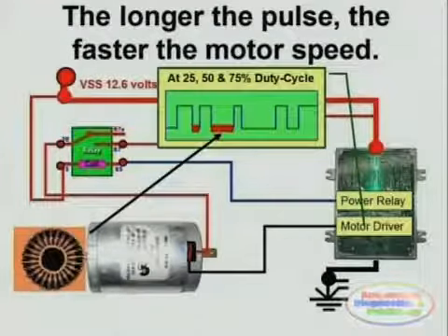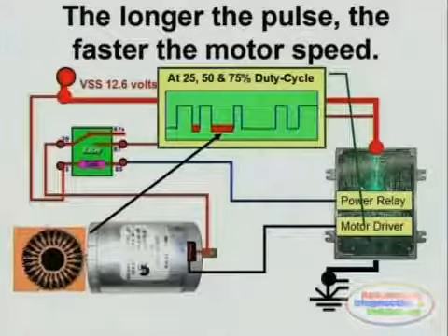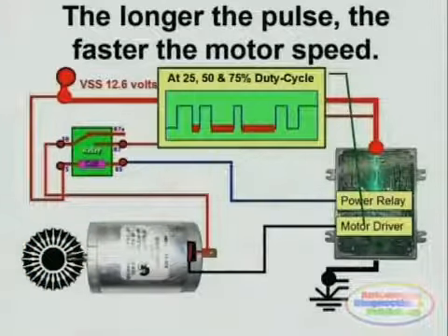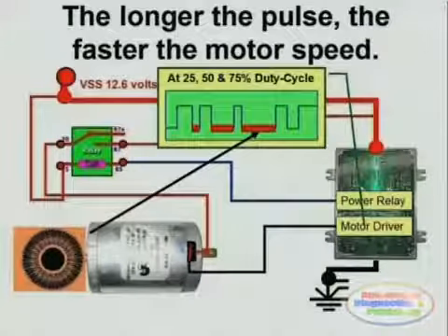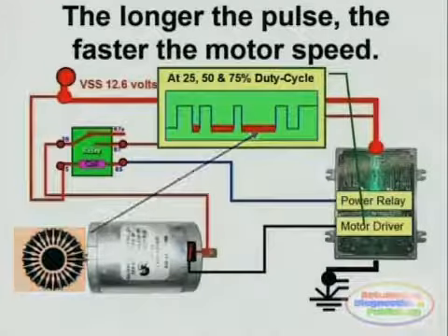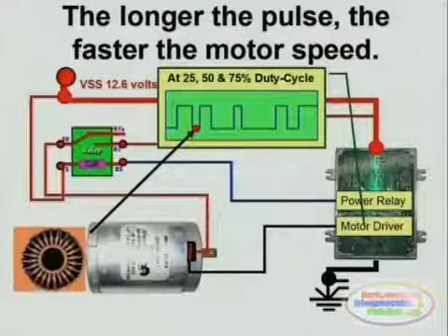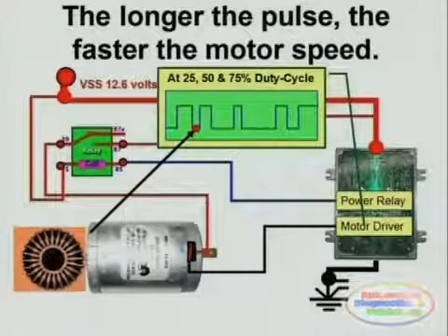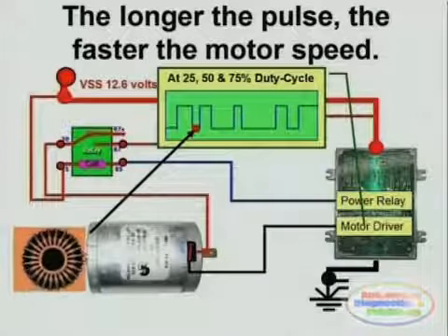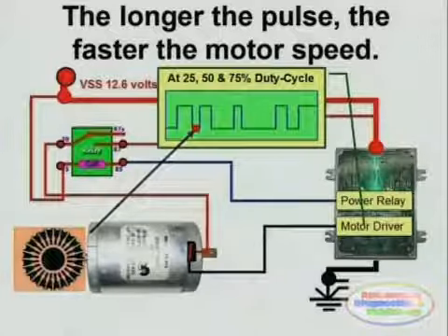Remember that this is a repeatable wider pulse, and it is not repeated here in this diagram for sake of explanation. But the longer the pulse, and now we can see that the fuel pump is turning even faster. The longer the pulse, the more work that the component is going to perform. Again, here we see a very short or very low duty cycle, probably in the range between 10 and 25%, and this will make the fuel pump turn very slow. You will need this condition again during a non-loaded idle condition.